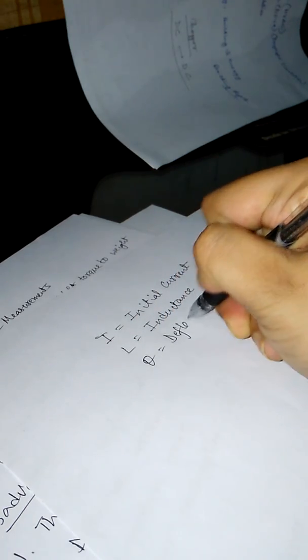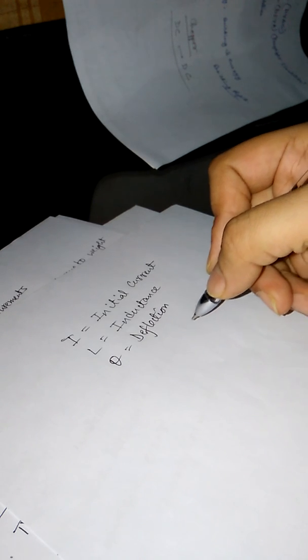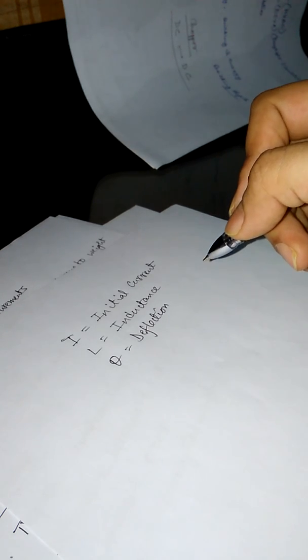We know that in the case of PMMC, the deflection is totally because of the flowing current. Suppose the value of current is increasing or decreasing from the normal current, then obviously the deflection is also going to change. So suppose there is a change in current, di.